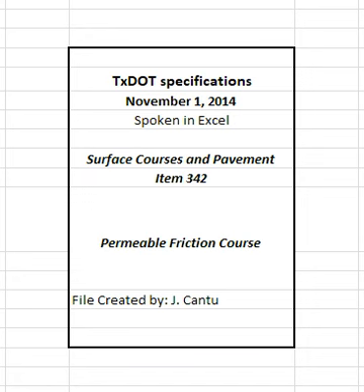4.9.3 Operational tolerances. Control the production process within the operational tolerances listed in Table 5. Suspend production and placement operations when production or placement test results exceed the tolerances listed in Table 5 unless otherwise allowed. When production is suspended, the engineer will allow production to resume when test results or other information indicates the next mixture produced will be within the operational tolerances.